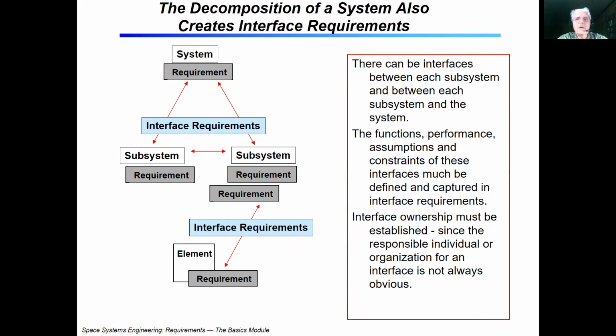A really good example of such an interface is the fact that a little single board computer like an Arduino Mega has digital I/O lines using what are called TTL levels. All right. Now, if one wanted to communicate with a different kind of computer, you probably need an interface which would translate those TTL signal levels to RS-232 signal levels. So that is an interface that you need to understand and be able to define if it is needed for that.